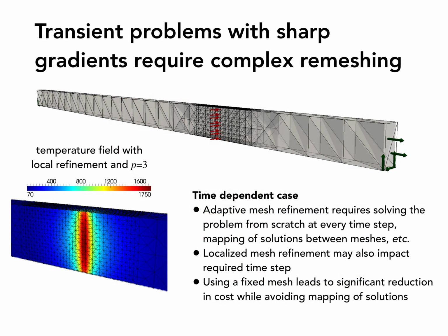And we said something about sharp gradients. So imagine you have a problem where you have a heat that is very localized. So you know that the solution at the point where you're applying the heat is going to be very sharp. It's going to be a very sharp gradient there. So if you want to solve this with the standard FEM, if you look close to the application of the heat, you have to really mesh so you can actually capture the gradient.